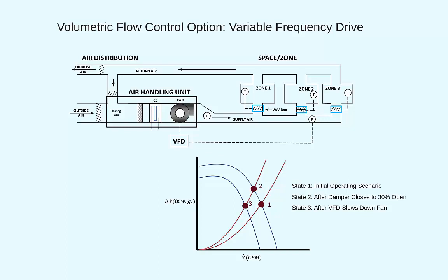Now, there are some limitations as to how much we can slow down the fan, just like we saw with hydronic systems. We typically don't allow VFDs to control fans to operate at much less than 10 Hz, that is 1/6 the max operating speed of 60 Hz. The reason we do this is that at such low loads, the motor efficiency and VFD efficiency drop off drastically. Thus, operating in such ranges can actually drive up the amount of energy being consumed. Sometimes it is deemed acceptable to take that energy penalty by reducing the speed below this point of diminishing returns, but we can save discussion for when such instances may occur for the LMS.